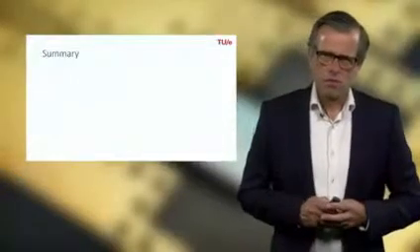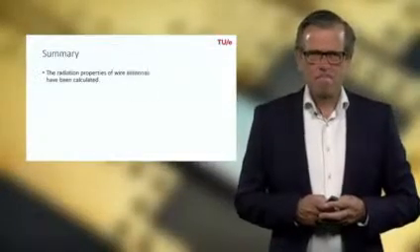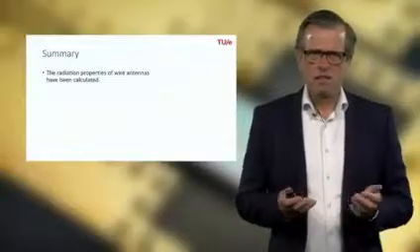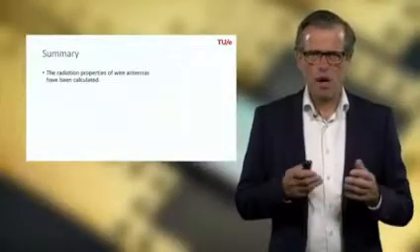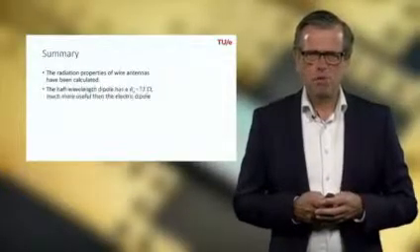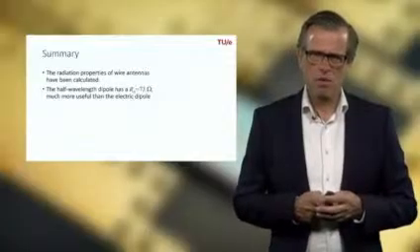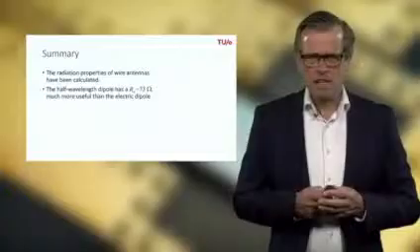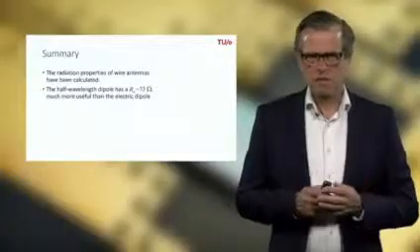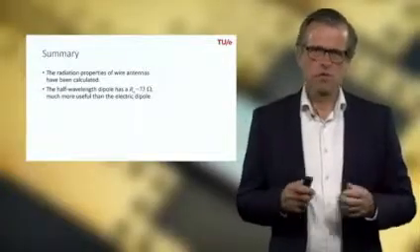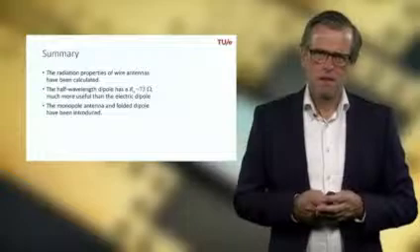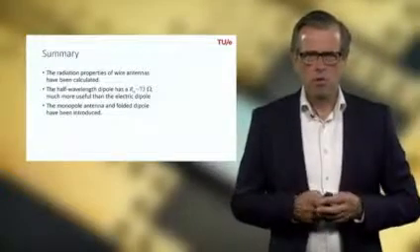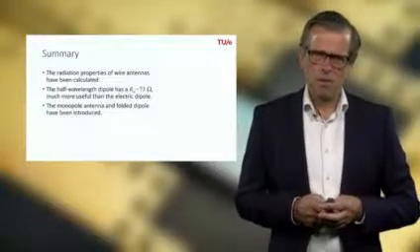Now, to summarize, we have calculated the radiation properties of wire antennas using our recipe. We have shown that the half wavelength dipole has a radiation resistance of 73 ohms, which is much more useful than the electric dipole. We also introduced the monopole antenna and the folded dipole.